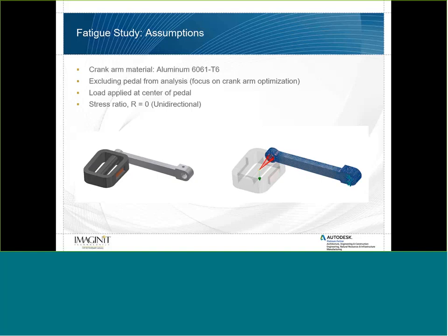I'm going to be excluding the pedal from the analysis. I'm going to be applying the load with some rigid body connectors. The reason I'm doing this is just because I'm not designing the pedal. The pedal could be a variety of things. It could be a pedal. It could also be a clip or a clip-type shoe. I'm not a pedal designer. I'm designing this crank arm, so I'm focusing my attention on the crank arm and looking at the load being applied to that specifically.